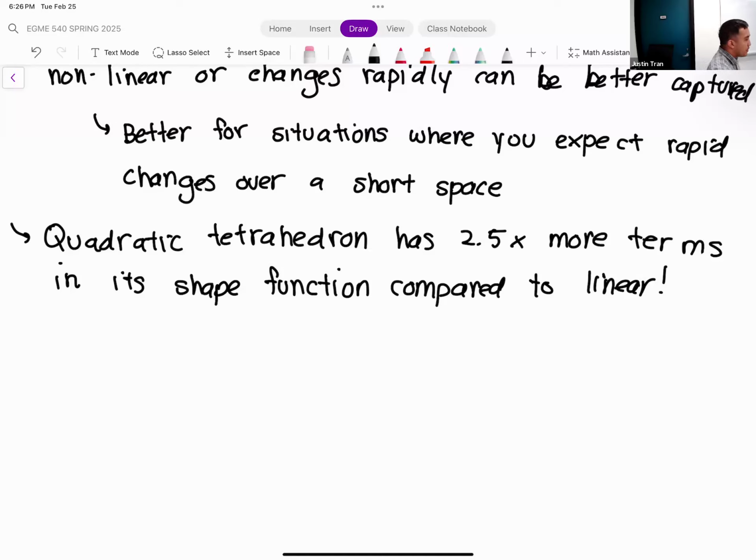Again, for the simulation that we're doing, it's going to be hard to really notice it, because when you hit solve, ANSYS doesn't spend that entire time just solving the linear system. There's a lot of time it takes to prepare the memory and all the matrices, and that amount of time is fairly consistent no matter how complex your mesh is. So it's hard to see this 2.5x cost for the simulations that we're doing, but for higher element count simulations, this absolutely makes a big difference. So this is something you want to be really careful about.